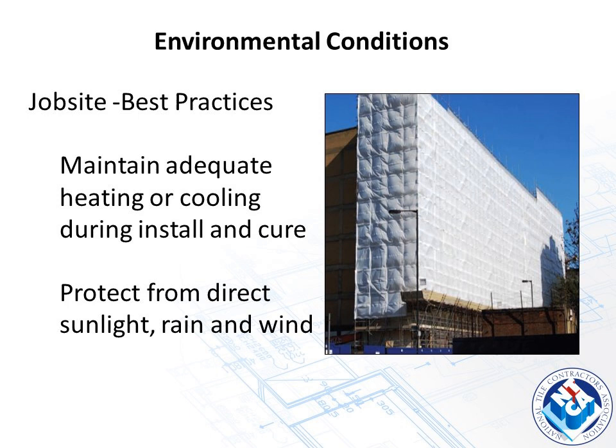In our case, when we're looking at large format tile, or for that matter, gauged porcelain tile, we're typically applying mortar to the substrate as well as the tile. Now, a typical gauged porcelain large panel tile could be 1 meter by 3 meters, or roughly a little over 3 foot by 10 foot in length. We're trying to apply that much mortar on top of the tile as well as on the substrate and keep it from skimming over. If it's open to the environment, the sun, the heat, the wind, those materials are probably going to skim over and you're not going to get a good bond. So protecting your installation can be critically important.